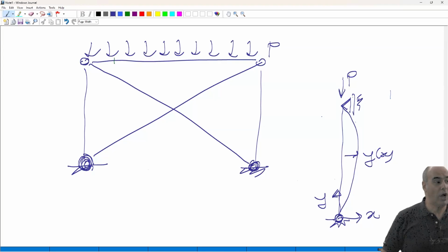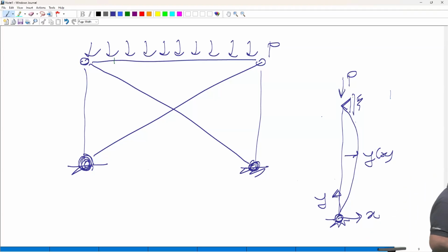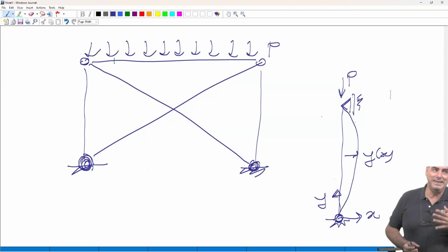It means that you don't see it up to the very moment where the applied load becomes equal to the buckling load. So it's something which occurs suddenly. In mathematics, you say it's catastrophic failure because you have something which does not exist, is zero up to that moment, and from that moment onward becomes infinite. It's a hidden type of buckling. In reality, this never occurs.